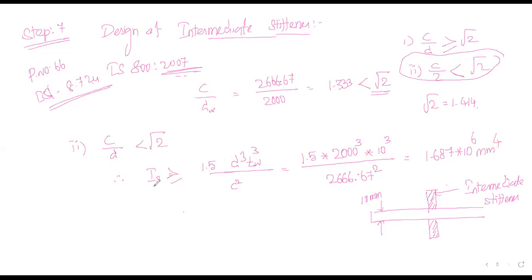If it is greater than this Is, then it is safe to carry the force. So let us try with the section: assume two numbers of 110 mm by 12 mm flats to be used as intermediate stiffeners.